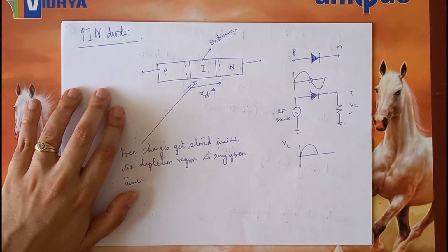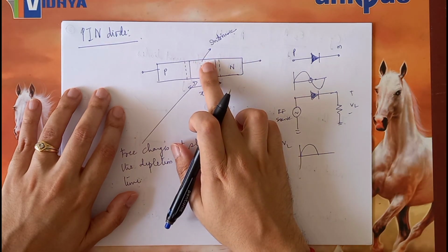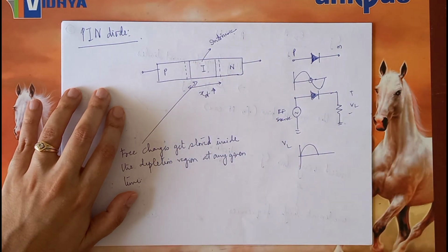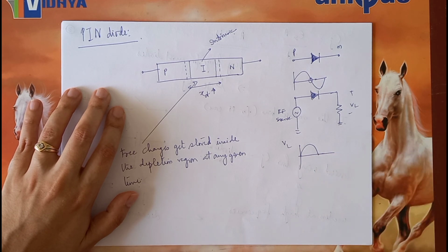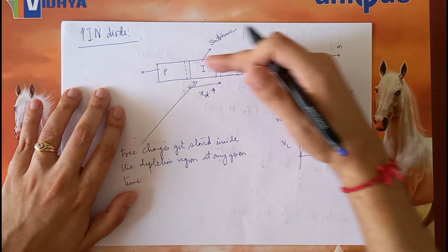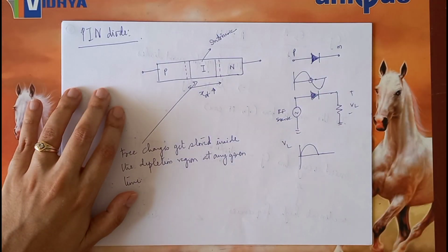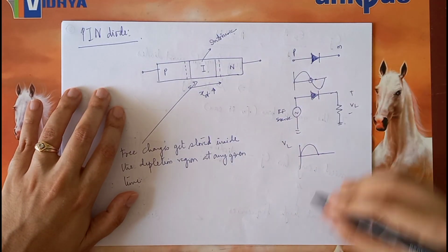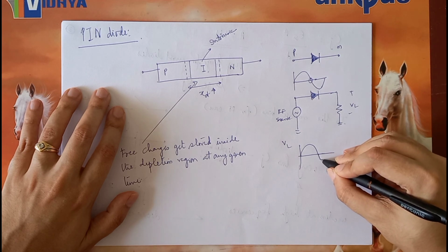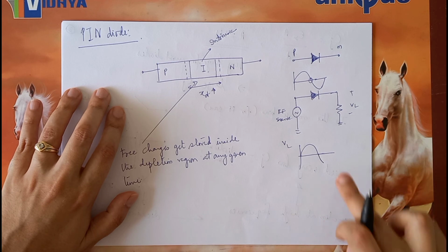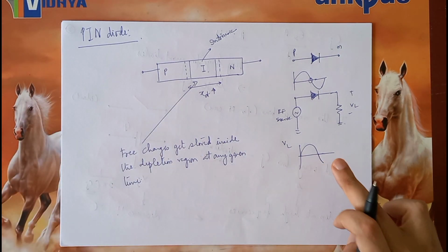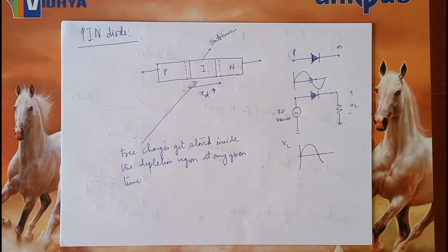The point now is that these charges will constitute a current. So therefore, what we expect is that in the reverse bias the voltage should go to 0. That will not happen. A current will start flowing in the opposite direction, which will try to follow what the input is. So for some time it may look as if the diode is still on, which it is.